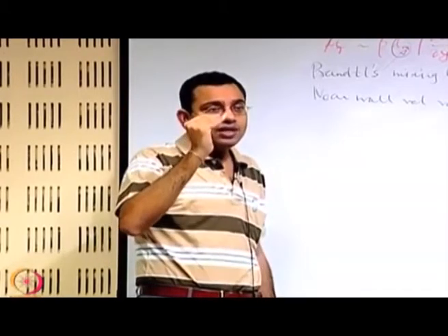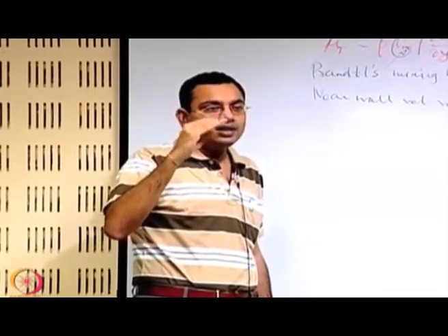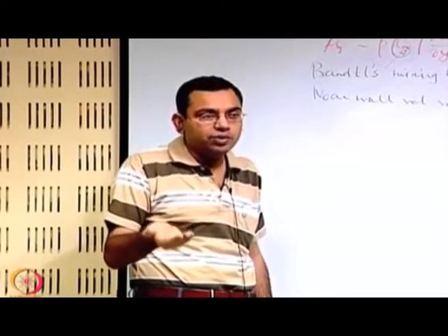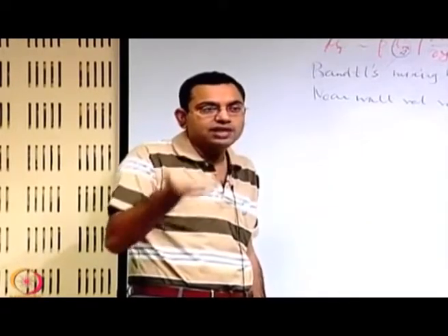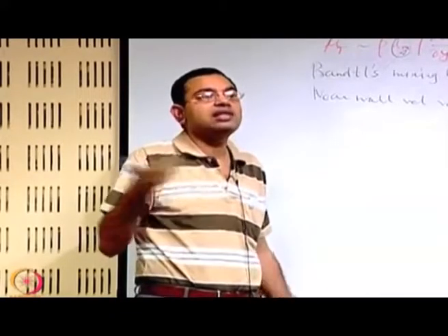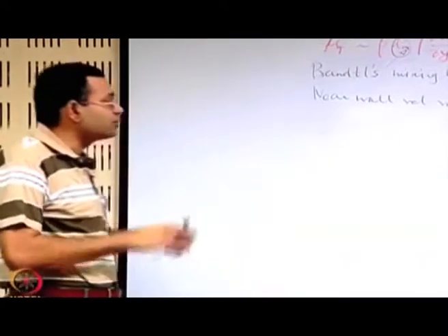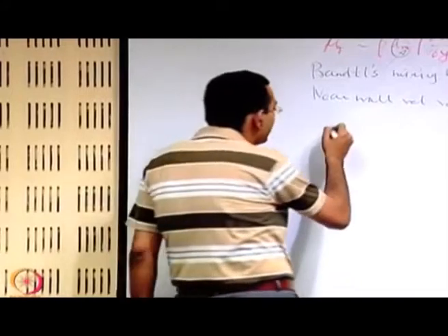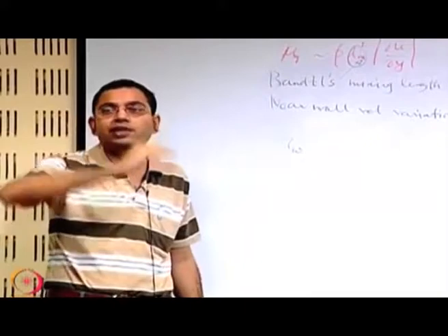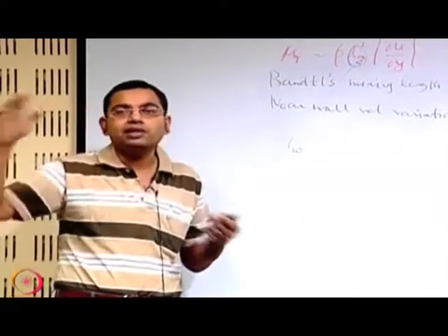As you go somewhat away from the wall, you will find a threshold location where the wall shear stress effect is not directly there, except that the effect of the wall has got propagated to the inside because of the molecular viscosity, but in terms of the stress, the turbulent stress is the solely dominating factor because fluctuations become more and more as you go away from the wall. So at that threshold limit, you can say that whatever wall shear stress was there has been transmitted to a layer where the value of the stress is now being dominated by the turbulent fluctuations.